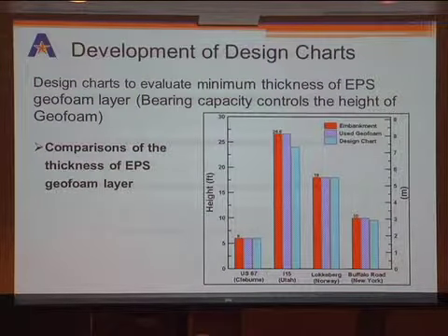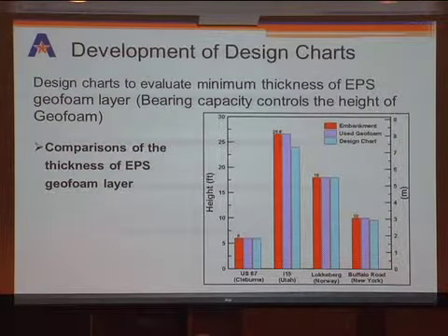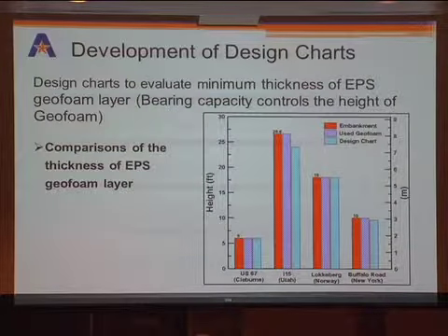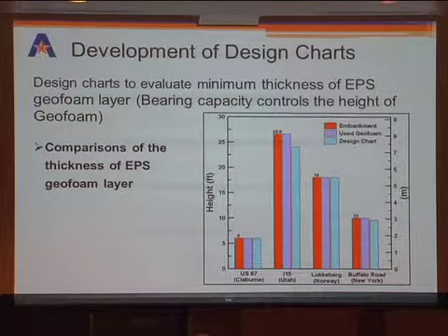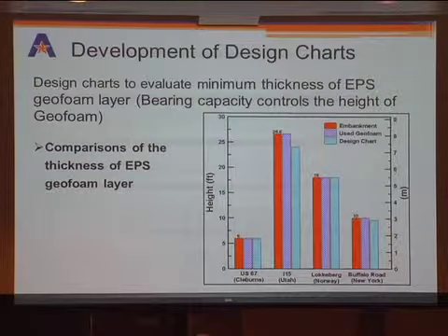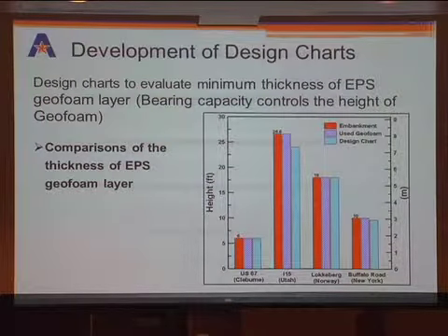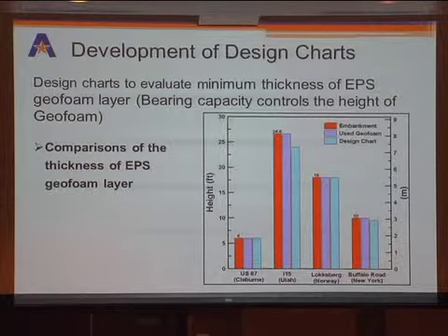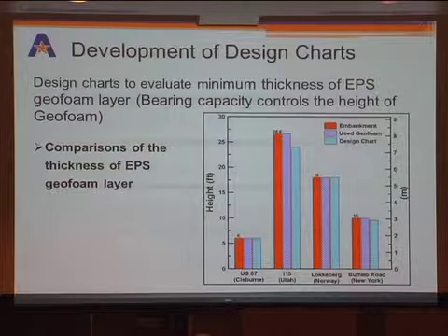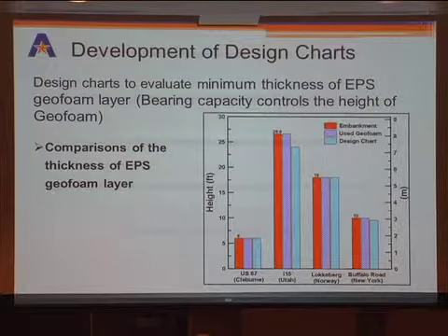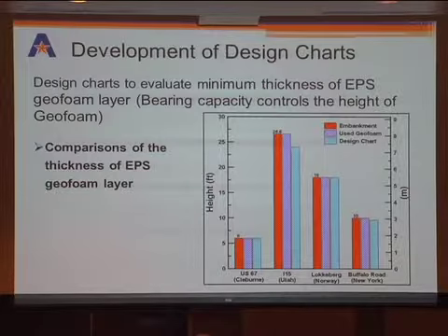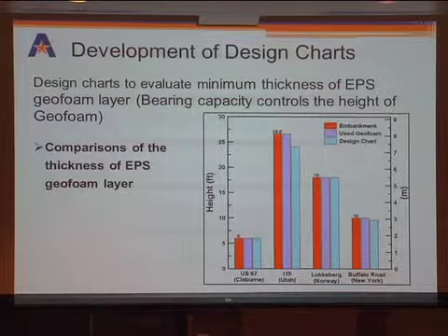from other locations. And I want to mention here, a lot of the work on geofoam comes from Norway. The Scandinavian countries sit on top of a mucky soil, almost like a quick clay, and it's one of the worst clays. The minute you dig within about 6 inches, you hit the high water table. And if you stir the soil with an auger, you will make that soil liquid. I think if you search YouTube for quick clay of Norway, there is a video that shows it.